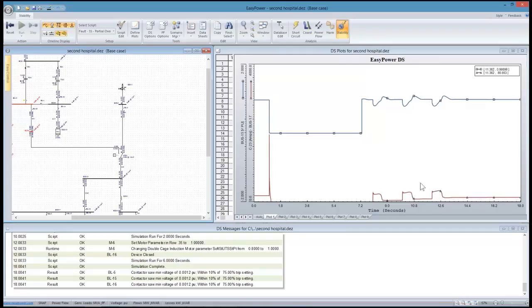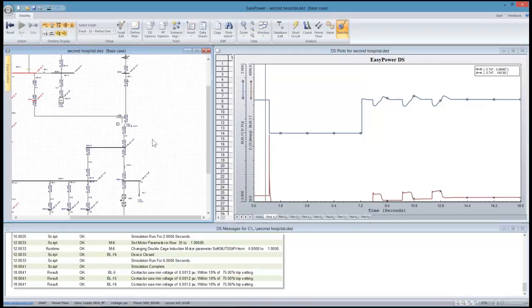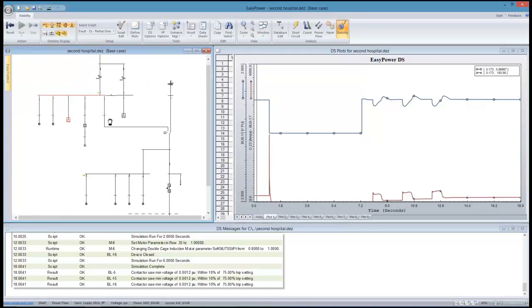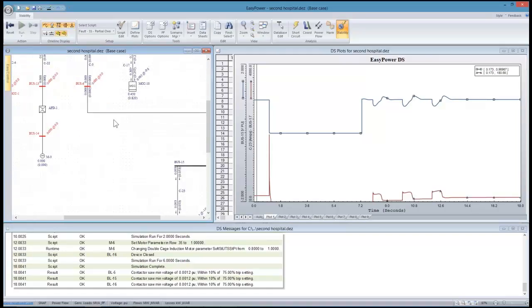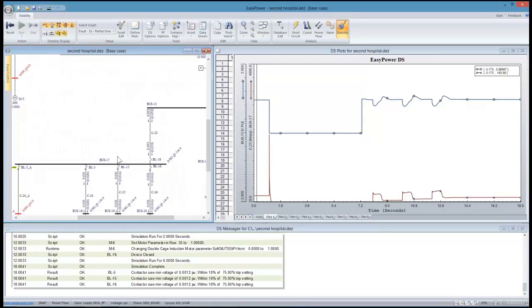So with that much of a delay between them, if we make sure that there's at least a 2 second span between the starting of each elevator motor, then all three would survive being on the standby generator power supply, which I thought was kind of fun to examine. And it looks at this not so much just from the generator controls, but from the system response and the ability to support loads coming on that basis.